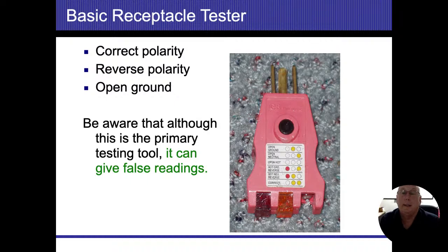The one thing that I have found, and I didn't test this personally, I just saw it in another video somewhere, is that if this 120 volt outlet is accidentally wired as a 240 volt outlet and it's properly grounded and you plug this in there, supposedly it's going to show normal. You're going to get 2 yellow lights and everything's going to show correct on there. If you get the more expensive testers, that's going to pick that up. I myself have never run into that, but who knows if I would have noticed it, because I don't take each outlet apart to look at the inside wiring.